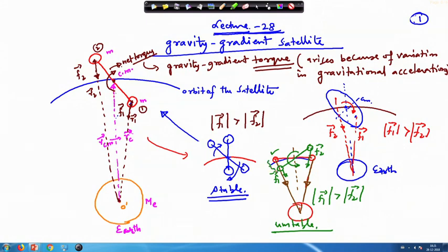You have given an initial disturbance, say by this angle, something like theta. So, this angle will increase over a period of time, it will not decrease. Okay, and therefore, this configuration is statically unstable, and dynamically, in this case we will have to do a lot more work before we finally come to whether it is dynamically stable or not. But once we can say that it is statically unstable, there is no restoring force, which means it is dynamically unstable. So, this thing we are going to analyze mathematically. Okay.